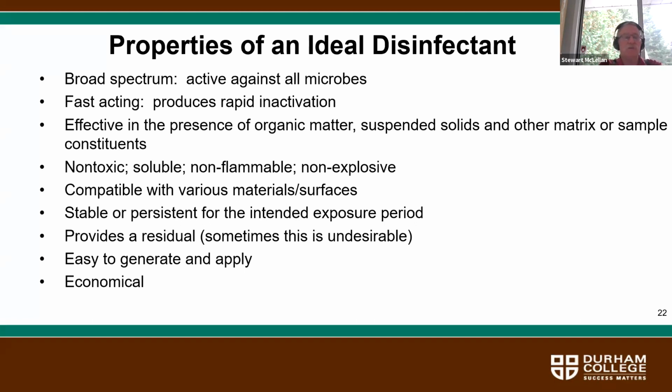Compatible with various materials and surfaces. Stable or persistent for the intended exposure period, and that's where your disinfectant demand comes in. You need your disinfectant to persist long enough to be effective against all the microbes that are present, and to provide a residual. Sometimes this is undesirable. There are cases where you don't want a residual, or at least not a significant residual.